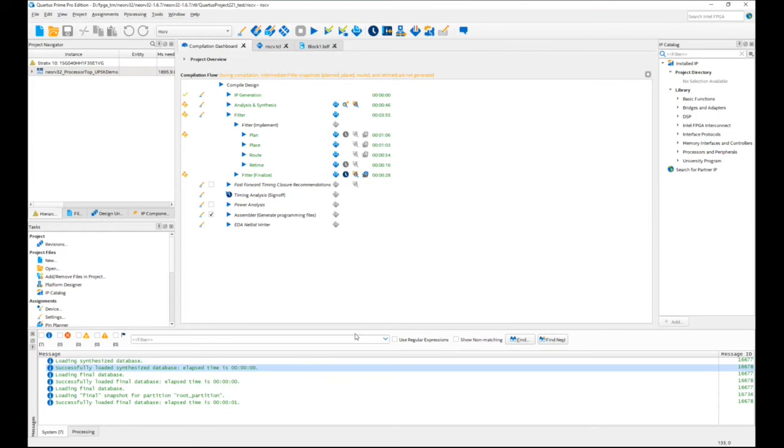Talk about it. So Quartus has this unique problem it's got to solve: you've got this design, and how am I going to place and route it? Now, if we were to take a trivial, contrived design, just one register, look at all the various places that one register could be placed inside of an FPGA. And you're going to come back to me and say, well, Steve, that's trivial. Any one of those solutions is just as good. Well, okay, you're right. But nonetheless, it has all those places where it needs to place and route that register somehow. And the possibilities start rising exponentially from there.